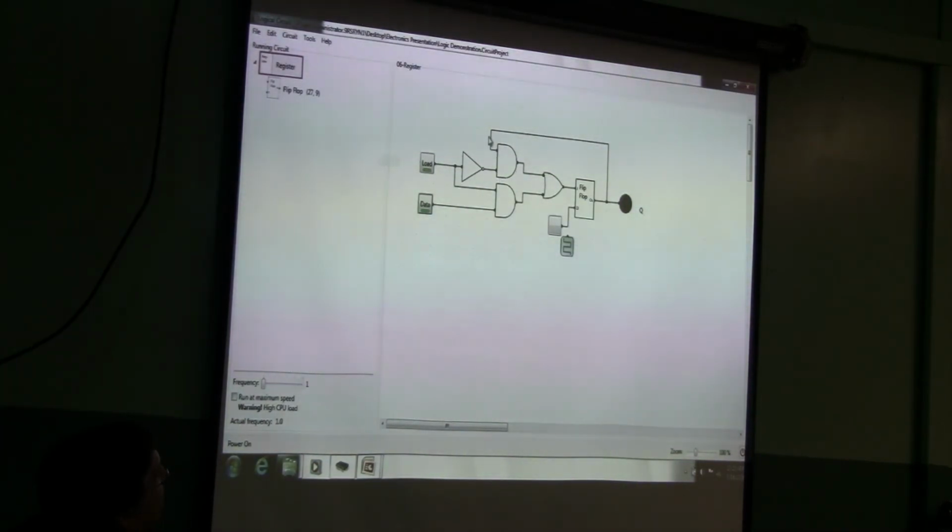And if this AND gate is off, then anything coming from the output is not going to do anything. So this OR gate is only going to get information from this AND gate. And this AND gate is going to get information because this is enabled with this input, and so whatever's on this input is going to get sent through. So if this is off, this is on, and this is off, so then this is off.